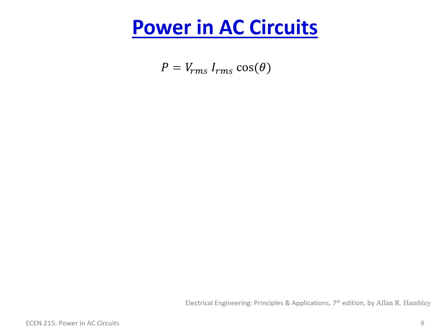So using that, we end up with this equation for power, VRMS, IRMS, cosine of theta, where cosine of theta is known as the power factor. If you ever work in an area where you're dealing with a lot of motors, three-phase motors, and so forth, you're going to see the phrase power factor. Like, this motor has a power factor of 0.9. Well, that is actually giving you what theta is effectively, because they're giving you the cosine of theta. It's going to be a number between, in the end, -1 to 1, which is truly the cosine of theta, where theta is known as the power angle.